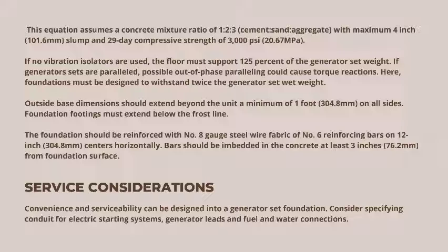Service considerations. Convenience and serviceability can be designed into a generator set foundation. Consider specifying conduit for the electric starting system, generator leads, and fuel and water connections.